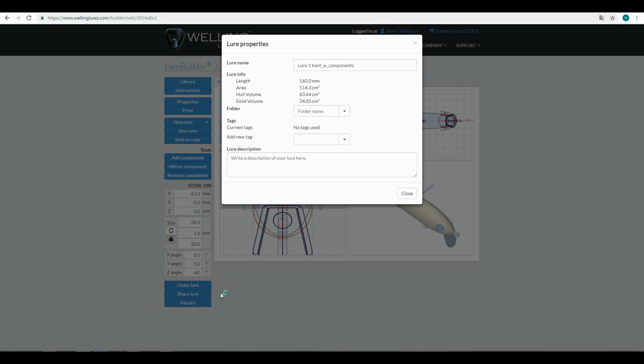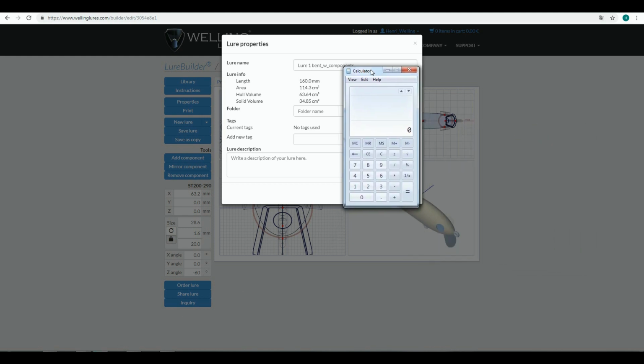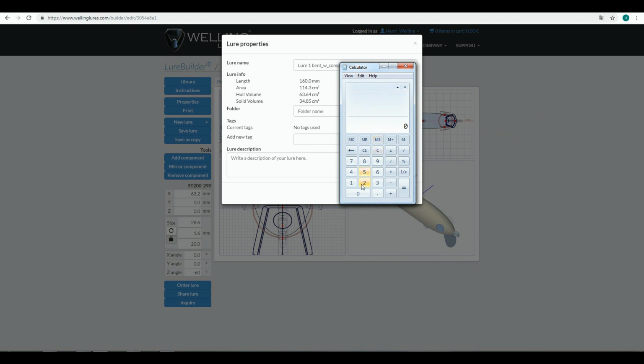And I'm planning to make this lure prototype from polylactic acid material, and I know that its nominal weight is 1.17 perhaps for that brand that I'm most often using. So I would then know that I already have 40.7 grams, 40.8 grams of weight from my 3D printed parts. So it would give me approximately 10 grams to play to my target weight.